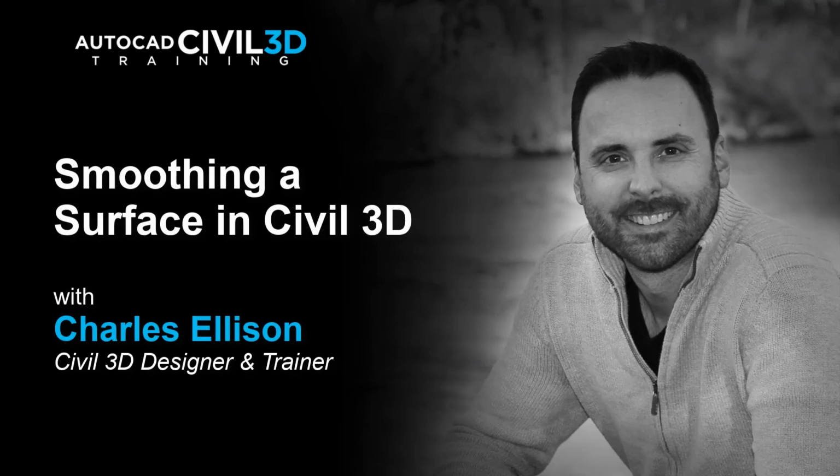Surface smoothing is an operation that adds points at system-determined elevations using natural neighbor interpolation. The result is smooth contours with no overlap. You perform smoothing as an edit operation on a surface. You can specify smoothing properties and then turn them on or off. When the smoothing is turned off, the surface reverts back to its original state. However, the smoothing operation remains in the surface operation list and it can be turned on again.